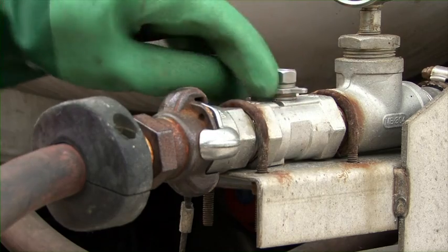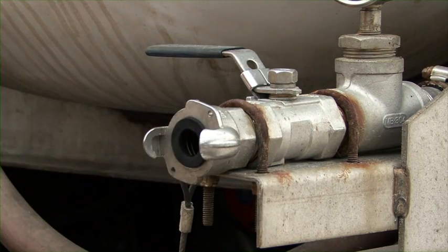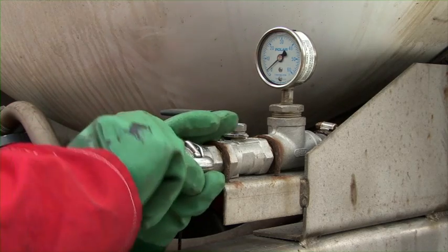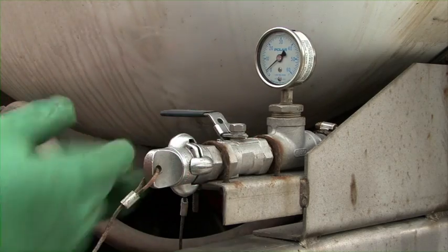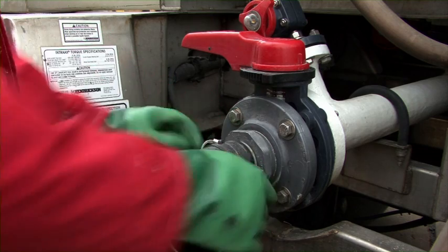Check the tank truck's internal pressure and relieve as necessary. Use caution when venting to prevent mist or spray of product. Secure the tank truck or other shipping container for shipment by installing plugs or caps on all openings.